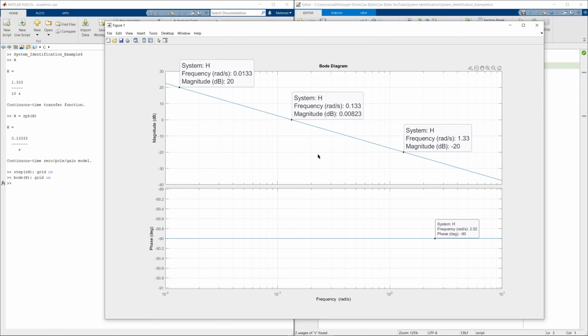But of course, different than the previous examples where we have the step response, which settles down to a final value, this is a particular different response. It will be helpful, of course, to also determine the actual response of your controller where you want to find it out if you don't know exactly what is going on in the panel. So this might be interesting if you do a step response for that one, and then you can see what the slope is of your response for your PI controller, or maybe the pure integrator as the controller.